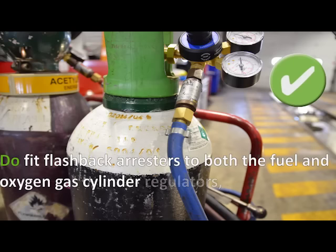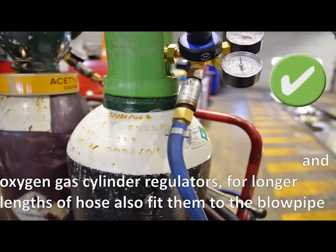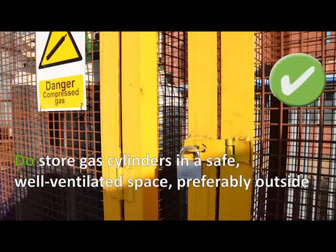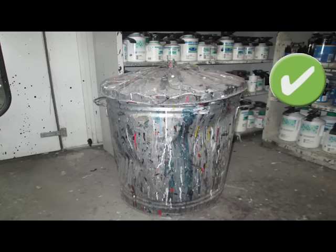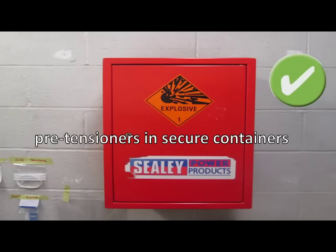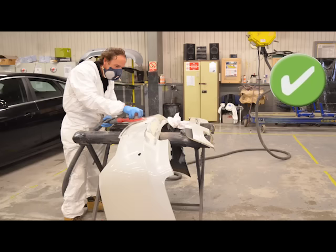Do fit flashback arresters for both the fuel, for example propane or acetylene, and oxygen gas cylinder regulators. For longer lengths of hose, also fit them to the blowpipe. Do store gas cylinders in a safe, well-ventilated space, preferably outside. Do dispose of contaminated cloths or rags safely, for example, in a lidded metal bin. Do keep airbags and seatbelt pretensioners in secure containers. Do use tools with built-in extraction or local exhaust ventilation when sanding organic body fillers.